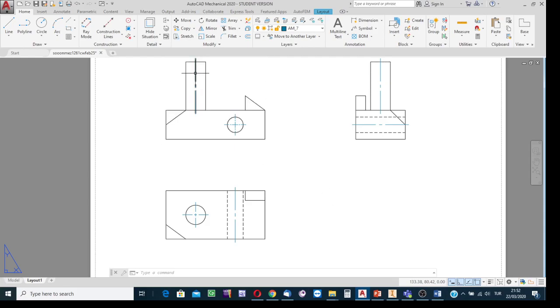But for this symmetry axis, the length is not so good, because along the longitudinal axis, having only one or two dash lines is a poor practice.